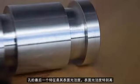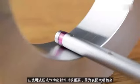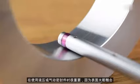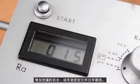The last characteristic of a hole is the quality of its surface finish. Surface finish is especially important when working with hydraulic or pneumatic seals, as a finish that is too rough will increase the chance of leaks or lead to premature wear of the sealing elements.